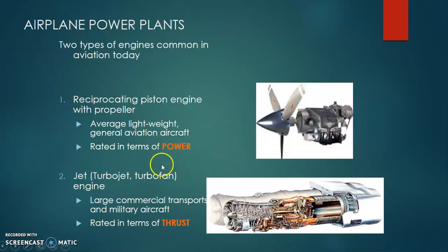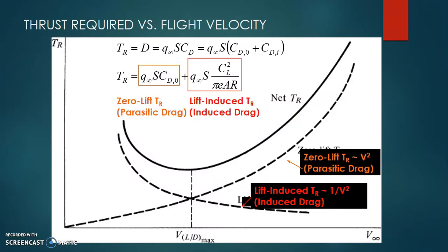Power applications are more suitable when you have smaller velocity and smaller thrust requirement operations, whereas jets and turbofans are more suitable for handling higher velocities, simply because at extremely high velocities, up to Mach 0.8, 0.9, these engines are not proven to be extremely rugged, and the failure modes in structures coupling with aerodynamics go up substantially compared to these closed, simple intake based turbofan or turbojet engines. All military engines will have a simple turbojet or turbofan because of the extreme demand of variation of thrust with time, as we saw here.